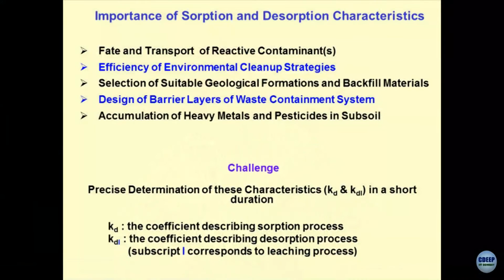Efficiency of environmental cleanup strategies. I think now you can understand why sorption-desorption mechanisms are important. If I have to show that after encapsulation, nothing moves out from the matrix in the form of cationic suspensions or cationic solutions, my immobilization is the best one. So, I have immobilized the waste to an extent where even after it comes in contact with water, nothing leaches out, clear? A simple cleanup strategy which you have created.